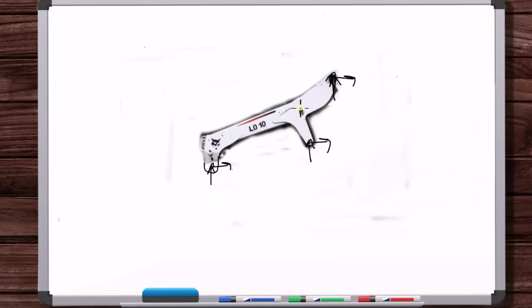We talked about how this is a rigid connection, how you can have a bolted plate or two bodies that are connected rigidly. If you have multiple bodies connected rigidly, but you didn't undo those connections, then those connections are internal forces. You might find this confusing. Well, how do I identify what's a connection that's internal forces in a body and what's not? When you're looking for areas of contact, that area needs to be exposed. If it's not exposed, then it's going to be internal.